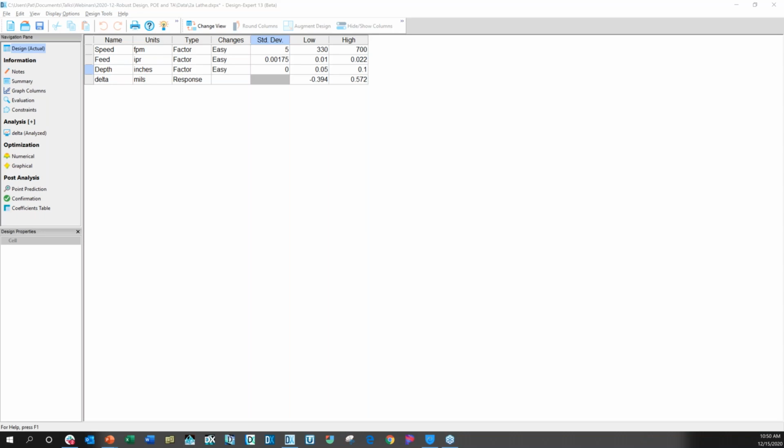Okay, somebody's asking how do you account for variation in the unknown factors like ambient temperature. I didn't have time to really go through how to do POE for the uncontrollable factors, but to very briefly state it, you'd have to be able to control the uncontrollable factor temporarily during the DOE. So, for example, I actually did a study where we were looking at some rheological properties and we were concerned about ambient temperature. We actually put the rheometer inside of an environment where we can control the temperature, and so we were able to control the ambient temperature while we were running the experiments.